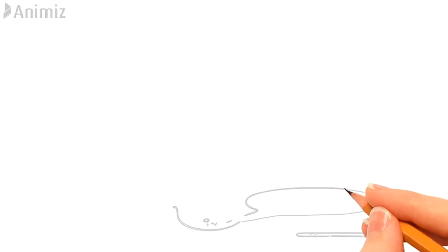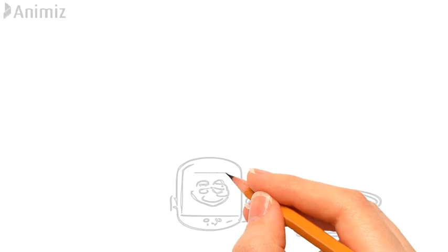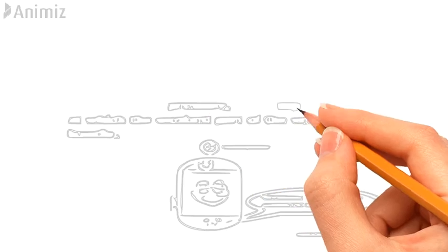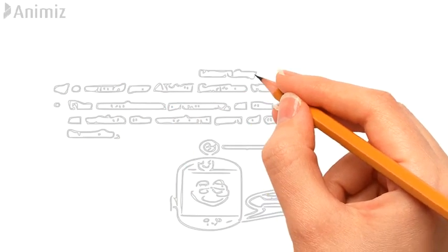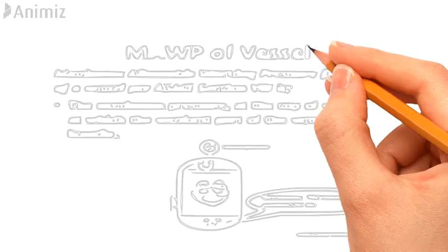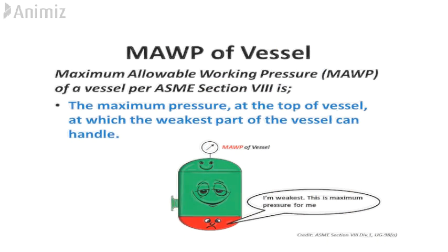Maximum allowable working pressure. The maximum allowable working pressure is the highest pressure that the vessel can withstand based on actual nominal vessel thickness, excluding the allowance provided for corrosion and loading other than pressure. MAWP has to be at least equal to design pressure. MAWP is commonly calculated for a fabricated vessel. During fabrication, availability of material and thickness of material used usually leads to a vessel exceeding the minimum requirement imposed by design pressure. For such a vessel, the MAWP is greater than design pressure.